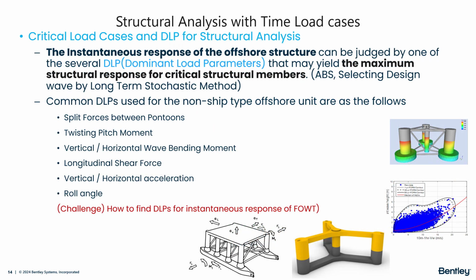So offshore code includes rules to determine the maximum structural response for structural members. For non-ship shaped offshore structures, the common design load parameters assume symmetry about an axis and require selecting specific time steps, such as when maximum split forces or pitch moment occur. A technical challenge arises in calculating these maximum split forces and longitudinal shear forces, etc., at each time step to identify the critical time step.